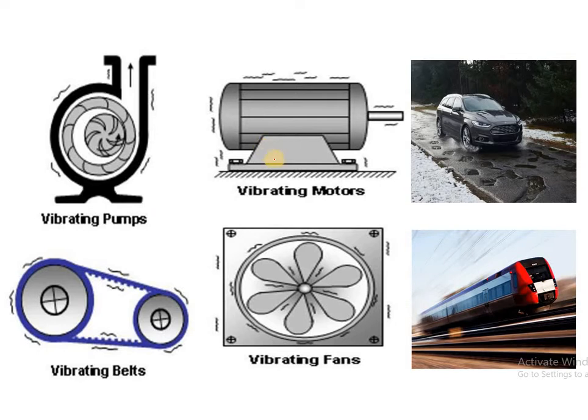Pumps, motors, fans, these all are designed very carefully and also manufactured very carefully by meeting the standard values. But at the same time, there is some amount of manufacturing error. We are providing some tolerances, due to that some amount of unbalance is generated in the system, and as we know, unbalanced force is nothing but the cause of vibration. So this is one of the causes of forced vibration.